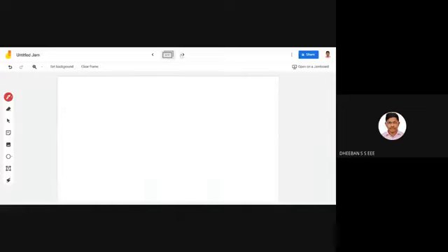Moving on to y13. It is nothing but the reciprocal of z13. You can directly apply the values: 0.02 minus j 0.06 divided by 0.02 the whole square plus 0.06 the whole square. Just solve it and tell me the value of y13.